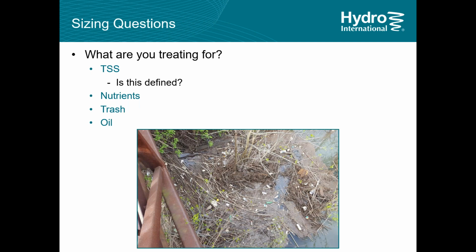There are a lot of questions that come in when it comes to sizing. Usually we get a call from an engineer or designer working on a project, and it's fairly vague sometimes. They just need a separator, or they need something to treat 80% TSS. And usually this starts a whole lot of questions going. What are you treating for? Is it TSS, and is there a definition of the particle size? Is it nutrients? Is it trash? Are you interested in oil? Because each one of these questions leads you down a different path of which piece of equipment is better or more suited to the situation and the application.